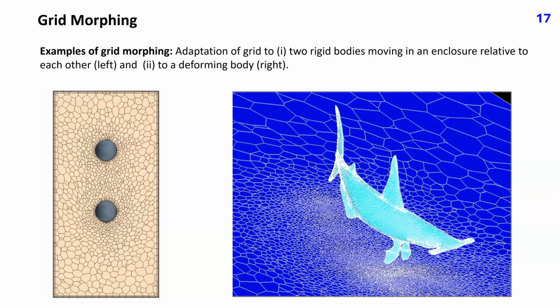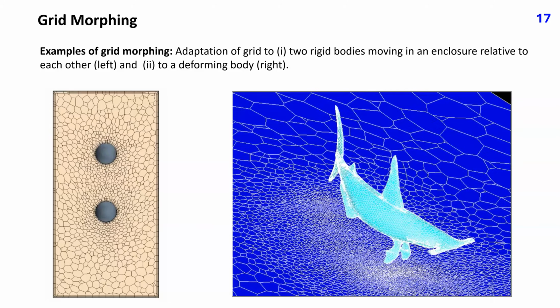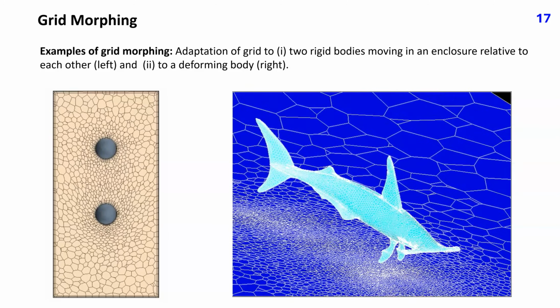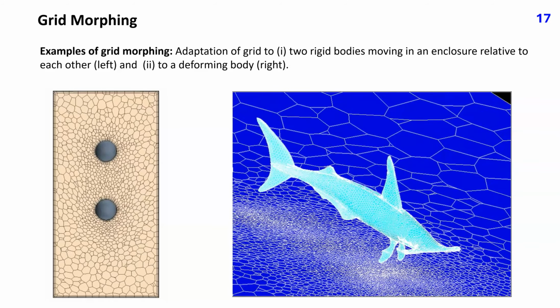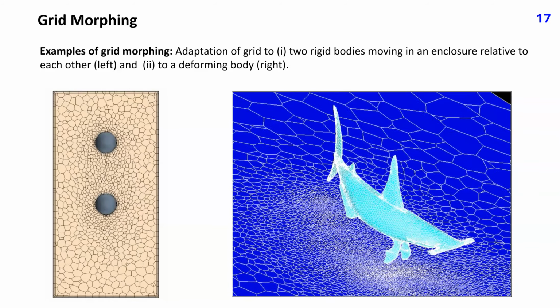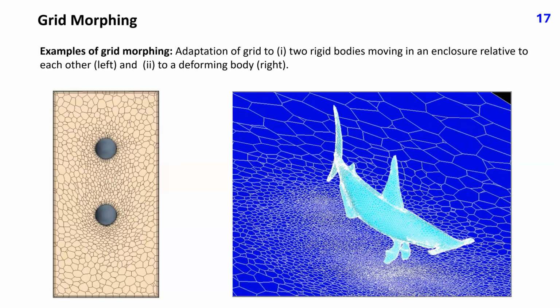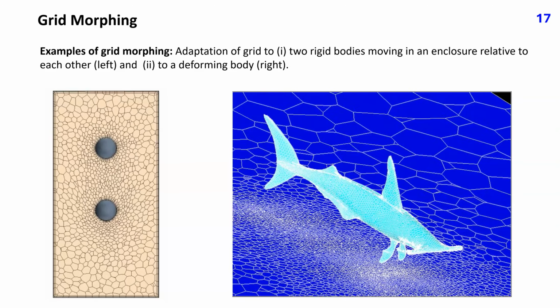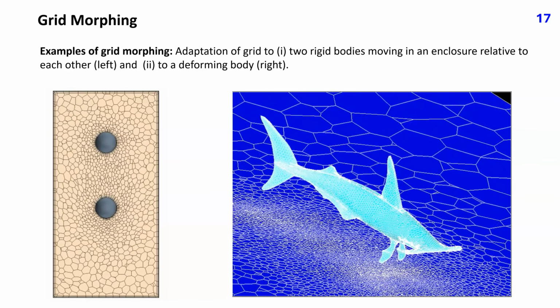This approach is suitable when the motion is of limited extent, ensuring that grid quality will not severely deteriorate during morphing. Especially body rotation over a large angle is critical. The other problem is that grid morphing usually requires solving additional equations to compute the coordinates of grid nodes at each outer iteration, which may considerably increase the computing cost.